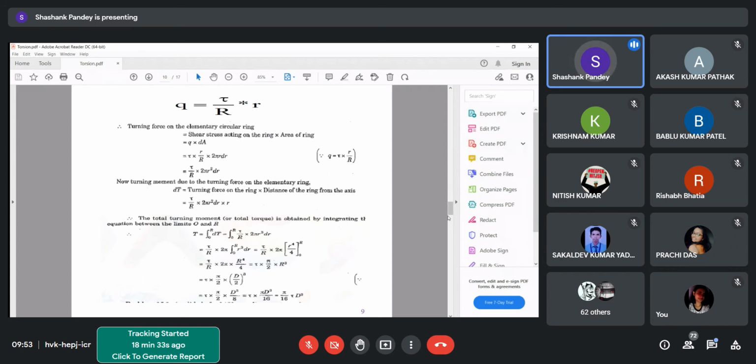First we calculated the shear stress, then we converted this shear stress into the corresponding force. The next thing we did is convert this force into the corresponding torque by multiplying by the radius, small r. Since this is a small value of magnitude dT, but we are interested in calculating the torque induced in the whole of the shaft,